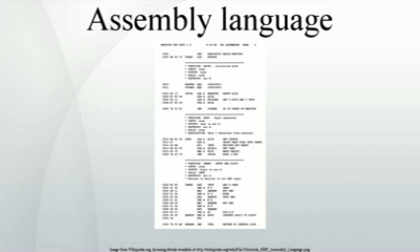A cross-assembler, see also cross-compiler, is an assembler that is run on a computer or operating system of a different type from the system on which the resulting code is to run, the target system. Cross-assembling may be necessary if the target system cannot run an assembler itself, as is typically the case for small embedded systems. The computer on which the cross-assembler is run must have some means of transporting the resulting machine code to the target system. Common methods involve transmitting an exact byte-by-byte copy of the machine code or an ASCII representation of the machine code in a portable format, such as Motorola or Intel hexadecimal, through a compatible interface to the